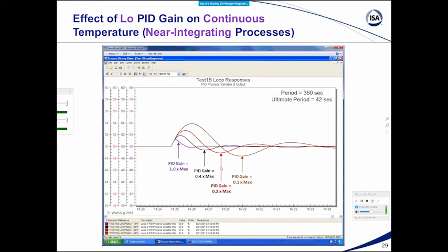Oh, it's bad. Oh, geez, I don't know what's going on here, but I know from control theory that high gains cause oscillation, so I'm going to decrease the gain. So they go down to a gain of 5, and now the oscillations are worse. They're completely perplexed. They don't know what to do. Really, the solution was to go with the gain of 50, and then they had tight control.